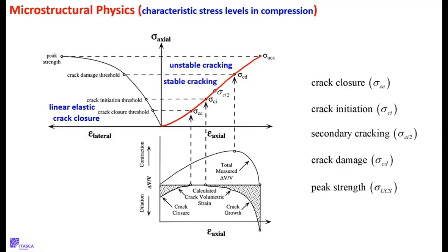Completely different rocks. A tightly formed sandstone from a certain quarry and a granite from another quarry are going to have the same UCS and the same E and nu, which means right away that these properties are not sufficient to fully characterize the strength and damage behavior of rock.